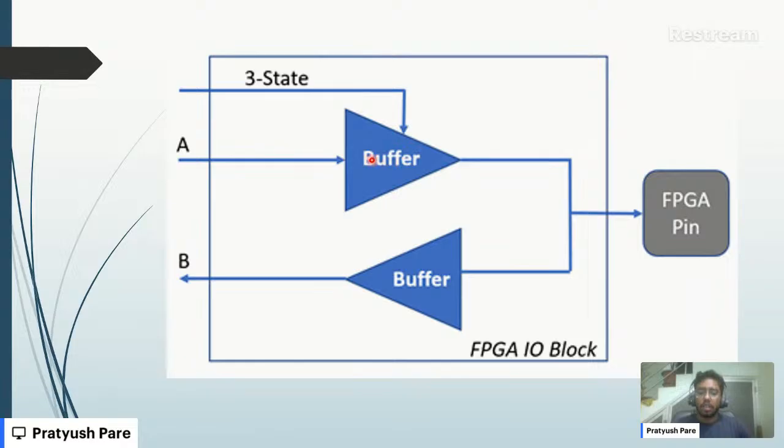I can show it for more clarity. If it is in the third state, consider it here as a high impedance node. So you have very high resistance between the two connecting lines, and that's why the data on this side will not get transferred to the other side, and that way the connection is broken and the tri-state buffer works fine.